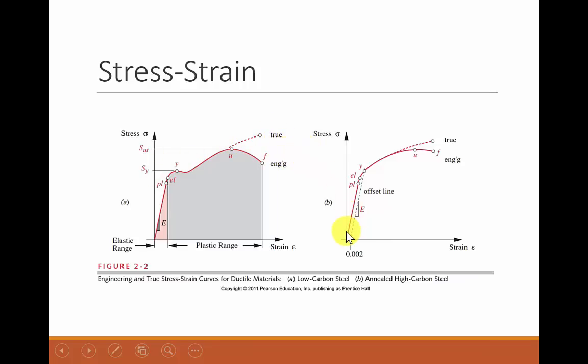For brittle material, it's not quite as easy. You don't get this hump where we return back down, and so you basically have to pick where you're going to call the yield strength. In other words, a ductile material gives us a warning. We pull on it, we pull on it, we pull on it, we continue to add stress, and then we notice this dip where it begins to stretch, and the strain becomes much more noticeable at this point. And that lets us have a warning. It hasn't failed yet, but it's on the road to failure. We better make some changes.